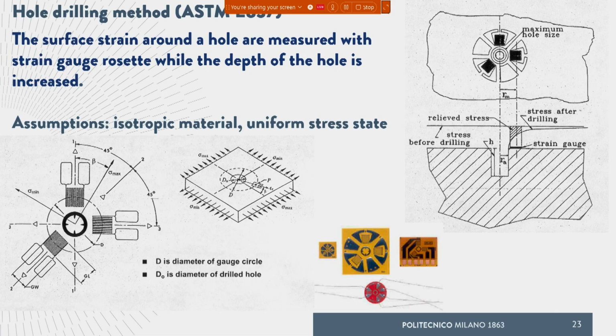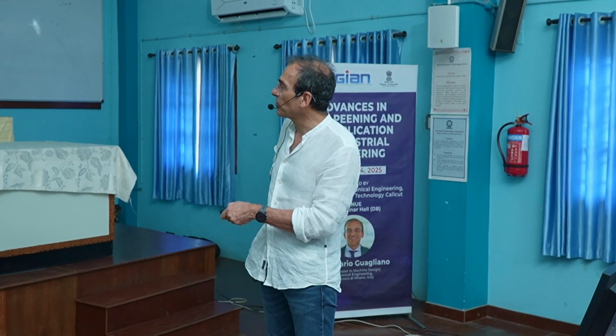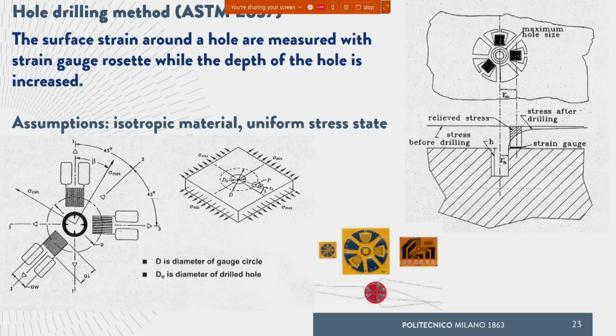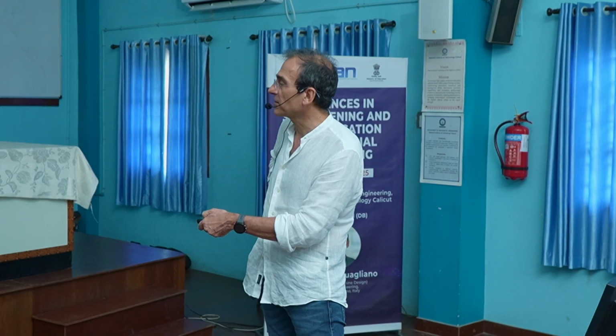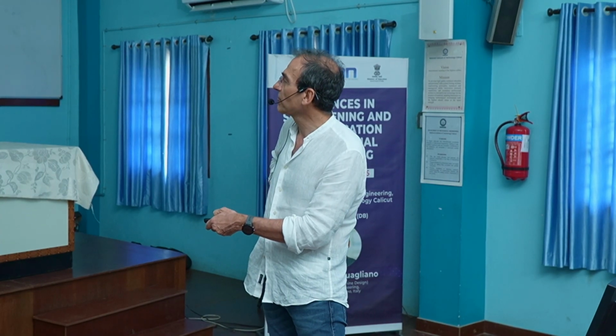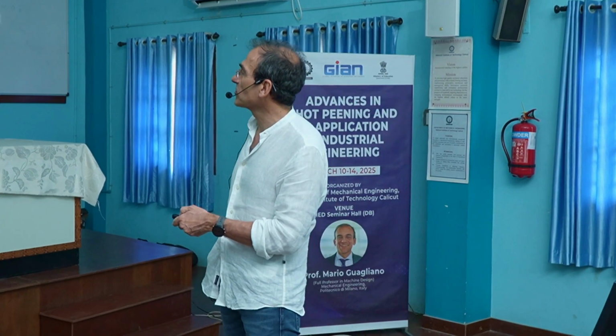This is the blind hole that is drilled. And then by measuring the deformation that is relaxed during the drilling, measuring the deformation at the points of the rosette, so not the same point of course, we are able, by means of elasticity theory, to relate the relaxed deformation to the pre-existing stresses at the point where we drilled the hole. And these are the formulas; I don't want to go into detail on the core formulas.